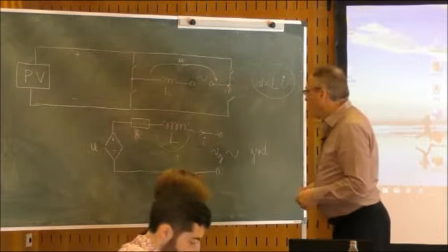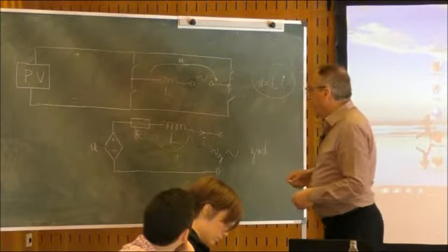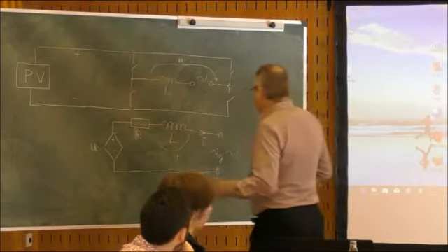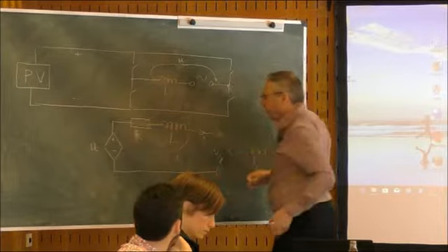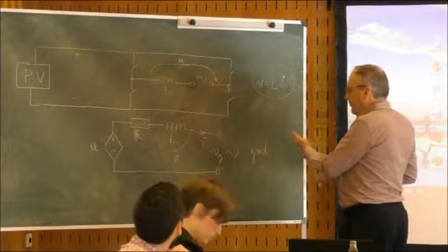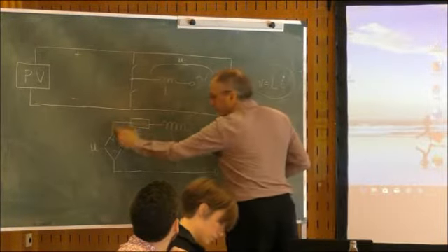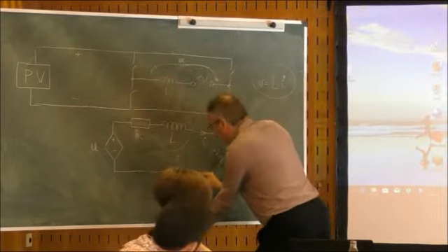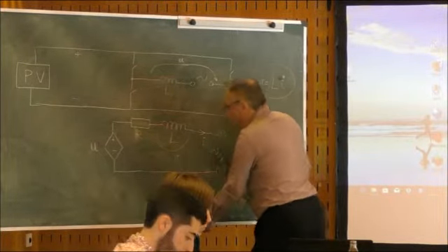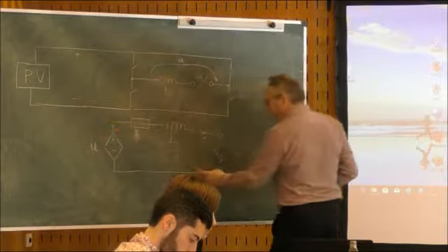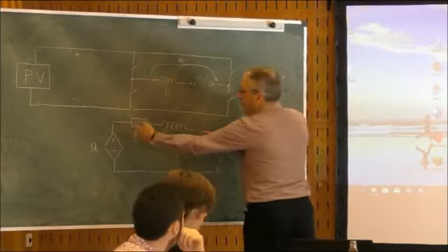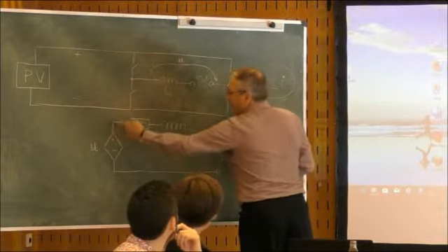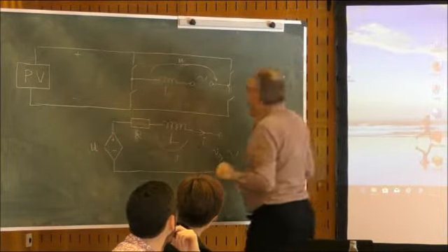So my system now is that I have this voltage between this point and this point. It is U minus Vg. Here I have the voltage U with respect to ground. I consider this to be the voltage 0. And this is the voltage Vg with respect to ground. So on this inductor, in total, I have the voltage U minus Vg.